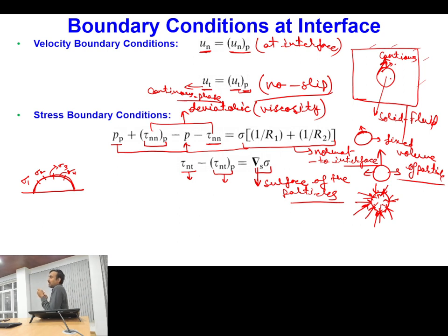Okay. At the same point of time, if you have a temperature gradient present in the system, this surface tension at the interface can be modified because of two reasons. One is because of the presence of surface contaminations or surfactants. So if surfactant concentration is different at different portions, then you will have different surface tension depending upon the surfactant concentration. Okay, so surfactants or any other contamination basically decrease the magnitude of the surface tension force. Second point is there can be variation in surface tension because of the temperature effect.